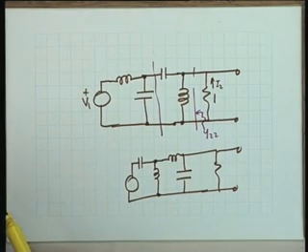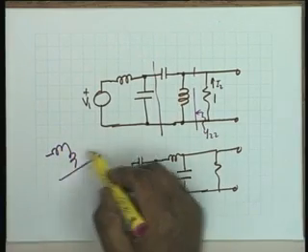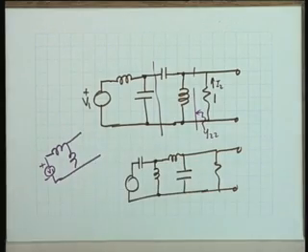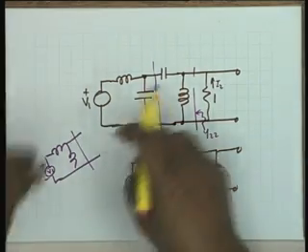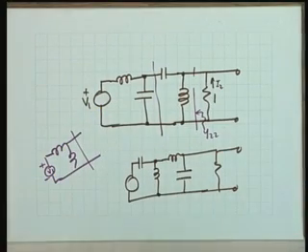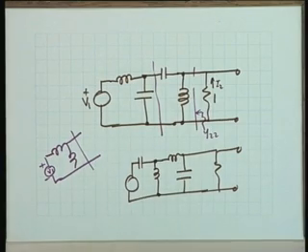So one in series and one in shunt. You see, I could not have something like this, as I had discussed in the class. Why? Because this is equivalent to 1 inductor. If we take the Thevenin equivalent, it will be a constant multiplied by V1 plus 1 inductor. Any other question? Can the capacitor and the inductor be in series? Yes, they could be in series.